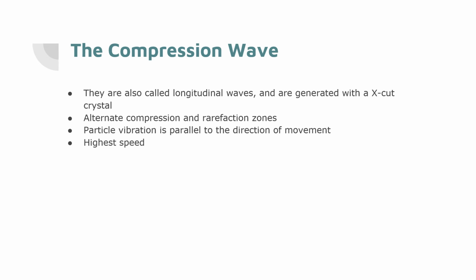Alrighty. So now that we've run through the calculations for this, let's do some theory as well. Now in ultrasonic testing, you get 4 main types of waves. The first one is the compressional wave, which is also called a longitudinal wave. And these are generated with X-cut crystals.